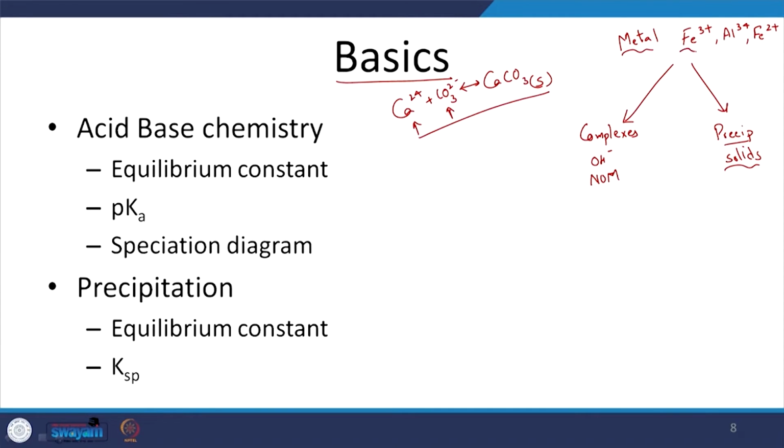So, we have metals that are soluble and exist as free metals themselves. We have complexes which are again soluble, but keep that in mind, maybe not greatly relevant in this process. Another aspect that is relevant is that you will have precipitation in the form of solids. The solid is not in the aqueous phase, so you can remove it, either by sedimentation, filtration or different means. Typically sedimentation is practiced after coagulation and flocculation to remove the solids in the context of lime and soda softening.